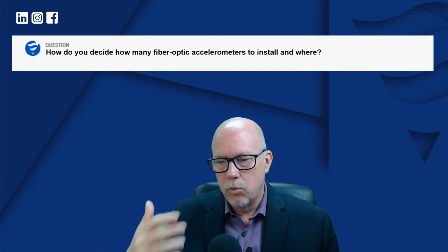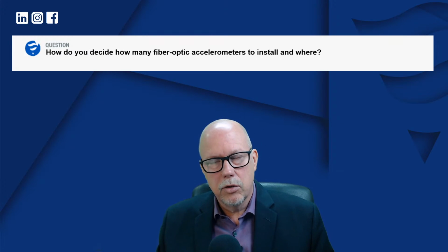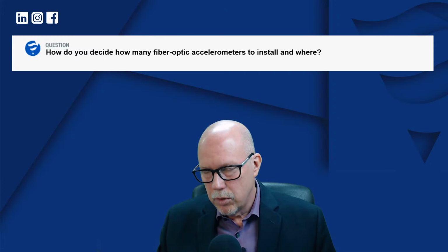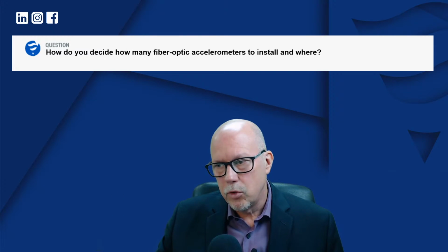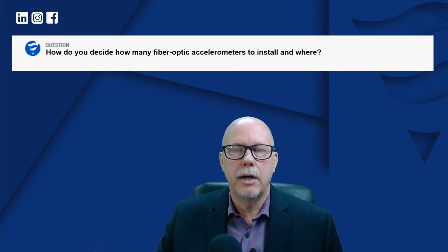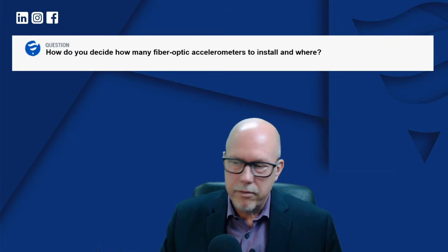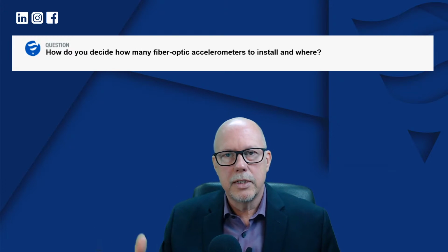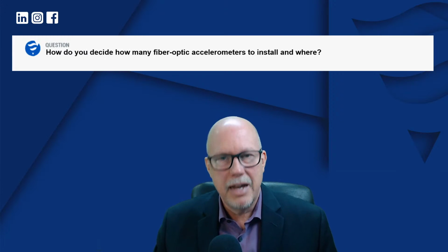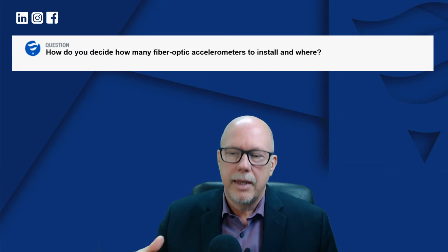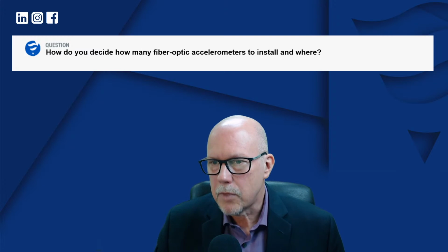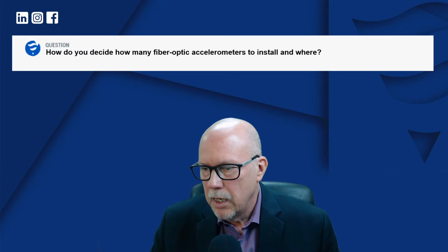But it means that the windings which are installed on the stator core and frame, well, that is suffering some type of impact. And we were able to show that if you went from the drive-in, you had some impact there. But as you move closer to the non-drive-in, you had a higher and higher level of impact, which told us that the stator was not properly fastened. It was actually moving, and it was giving a jolt at every so many milliseconds. And that high energy jolt was actually showing up on the end winding.